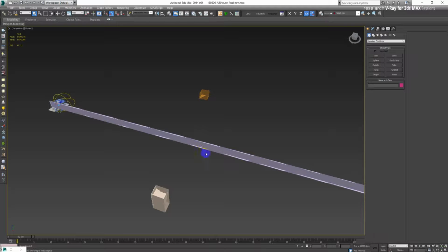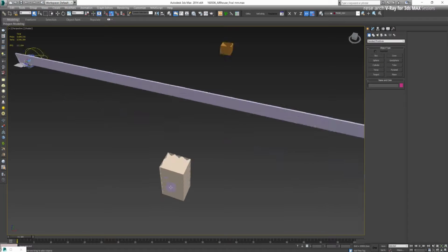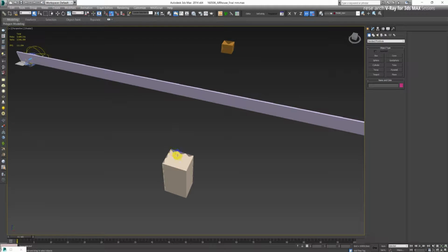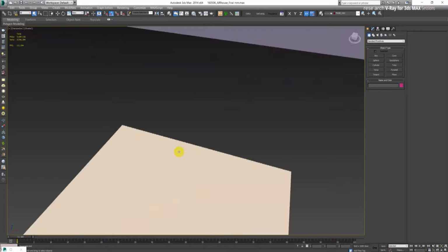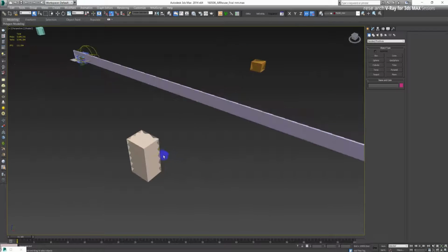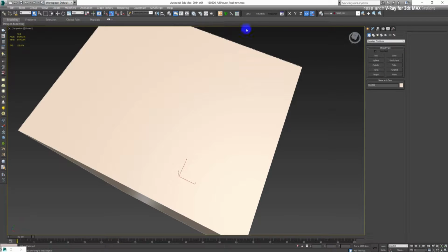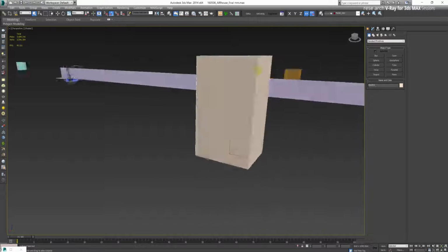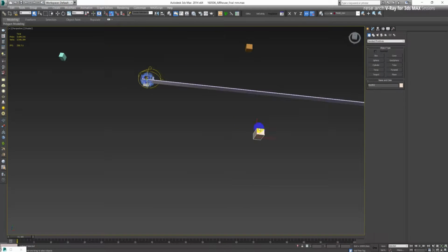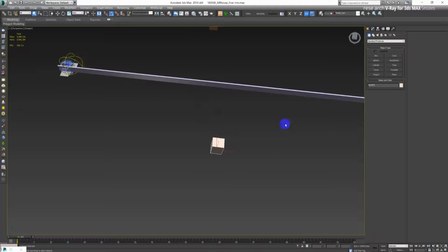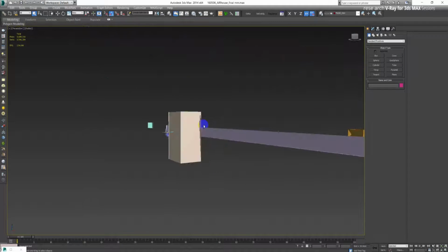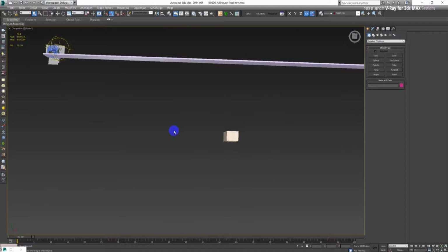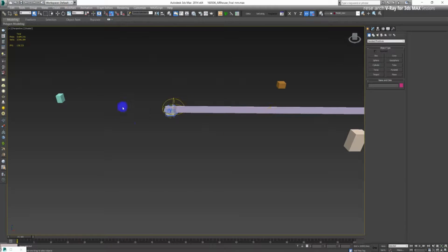And if I now go to perspective, and I'm trying to be orienting in here, you can tell that the viewport is actually being really destroyed. So this shouldn't be happening, and if this is happening, you can tell that you don't have correct units. This actually shouldn't be happening, because you cannot model and you cannot really go close, and this is not comfortable to be handling this type of scene. So when this bugging happens, you should re-import your scene to bigger units.